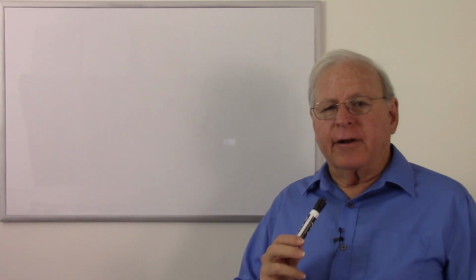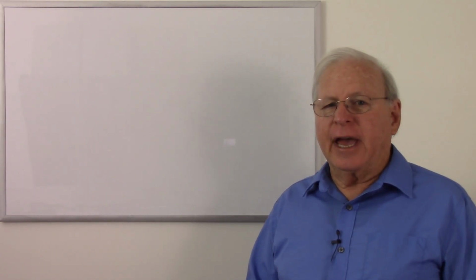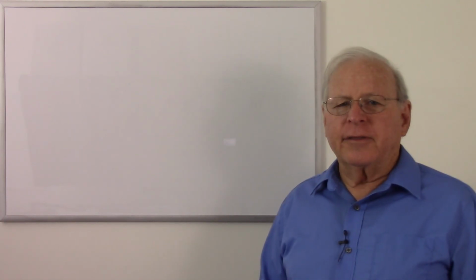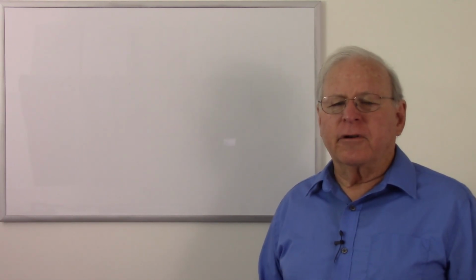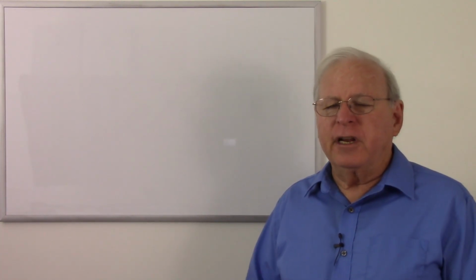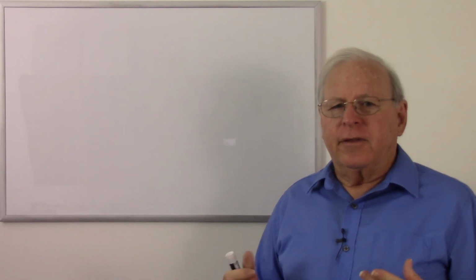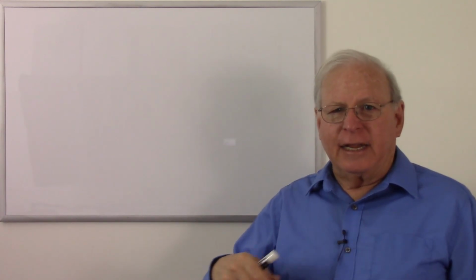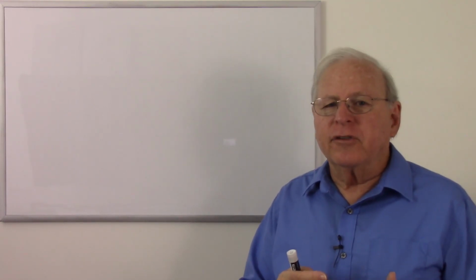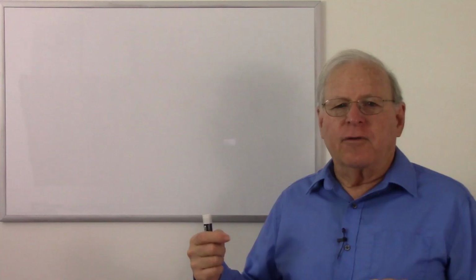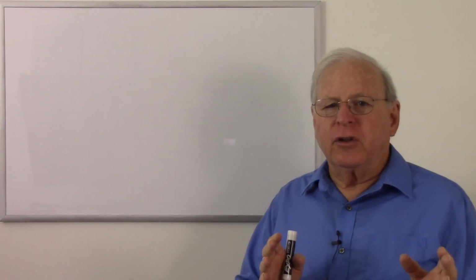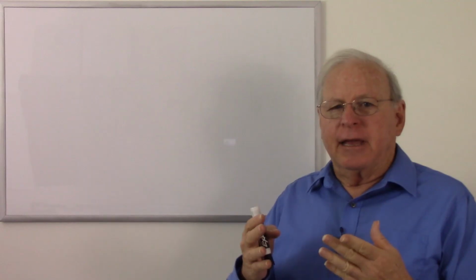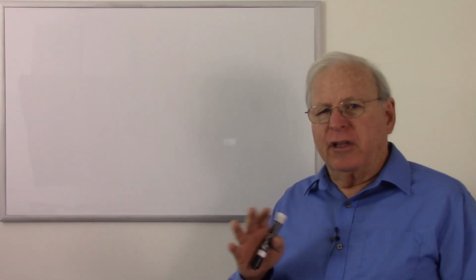One thing to note about a phonograph pickup is we have to deal with the equalization on the record. I'll talk about this in detail when I talk about phonograph players in a subsequent video. But to overcome the noise on the surface of the record, as we drag that needle across the record, of course, we get noise. And that noise is greater at higher frequencies than lower frequencies. So what they do is they boost the high frequencies on the record, and then when they play back, they boost the low frequencies to compensate.